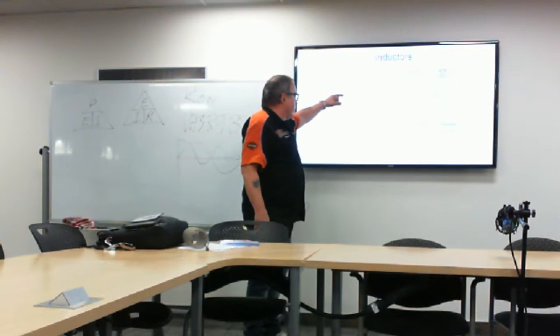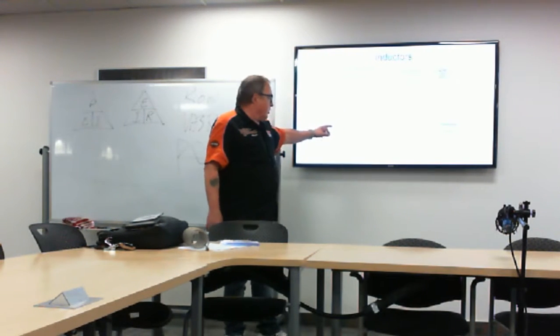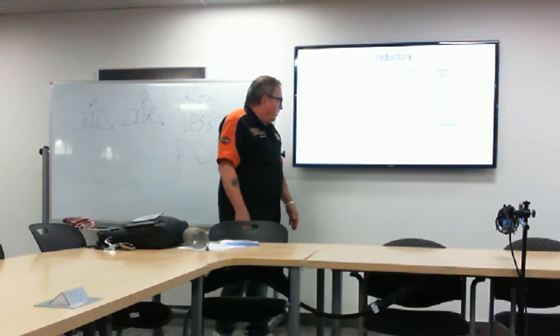Okay, then the amount of inductance is influenced by a number of factors. Yes, the spacing between the turns, the diameter of the coil, the number of coil turns, size of the wire used, type of materials inside the coil. All of these are factors. That's a powdered core, iron core for higher inductance. The highest is soft iron core. Small diameter, larger diameter, wide spacing, close spacing.